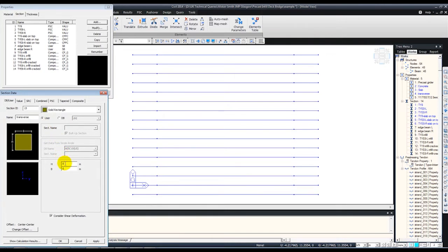What I'm going to do is to make it a little conservative approach. Instead of taking the overall height of the thickness of the slab, which is approximately 900 millimeters, I will take only the top bit as the transverse element thickness. So just 0.15 meters, 150 millimeters, and I'll divide the grillage into 1 meter segments.